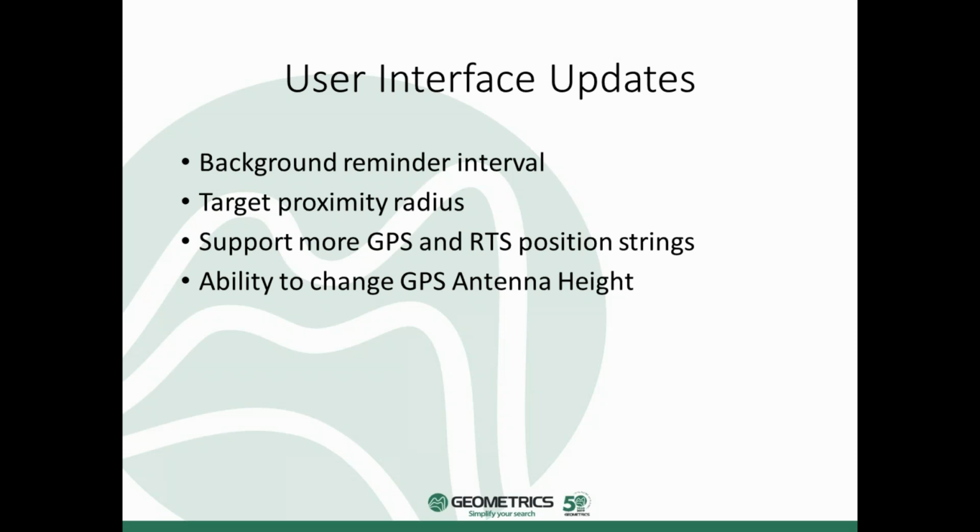And so perhaps in some places with varying geology or changing soil moisture conditions, the project geophysicist would request the field crew to collect backgrounds, say every half an hour, or if they think that 2-hour backgrounds are still acceptable at their particular job site, they can change it to every 120 minutes. So it allows a little bit more flexibility.